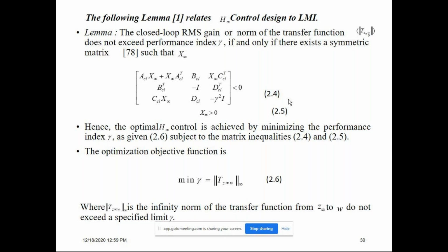Your grid code compliance, remember, sometimes in Gujarat they are now flailing with the grid code compliance for the wind total being generated. They are unable to connect to the grid in a very significant manner. The LVRT compliance is not there, and a lot of defects, a lot of flaws are there.